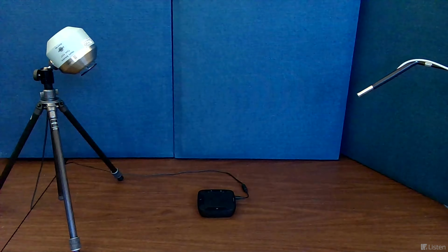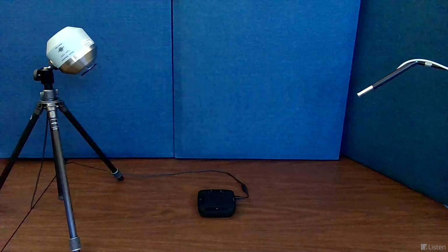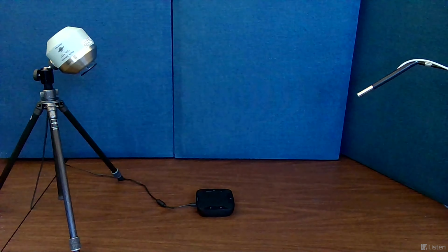This is a typical setup for testing speakerphones according to TIA 920B. In this case, the lip ring of the mouth is 50 centimeters from the device under test, and on the other side, the microphone grid is also 50 centimeters from the device under test. In this view, you see the speakerphone oriented towards the mouth, and this is the arrangement for sending measurements. When it's time to do receive measurements, we can turn the speakerphone 180 degrees and point it towards the microphone to do the receive measurements.